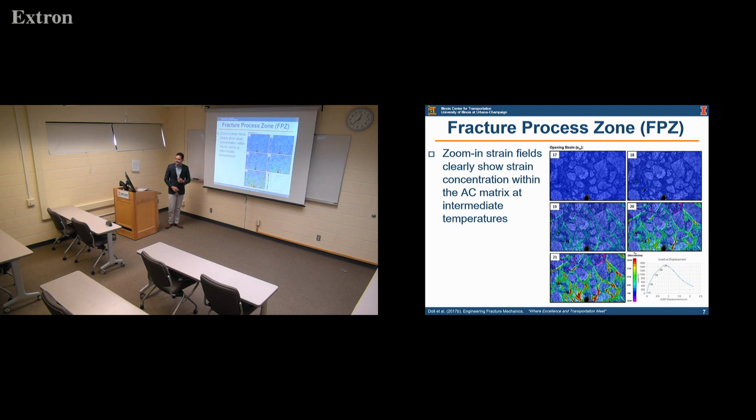Basically, when we apply this technique to the IFIT, we can see the image that we see on the screen. We can measure how the fracture process and how those strains are developing before that microcrack propagates. Here you can see 5 images that I selected of one specimen that I tested before the material fails. At image 17, nothing happened. I haven't started the test yet. And in image 21, we are at the peak load of the IFIT specimen, so we have the full development of the fracture processing.